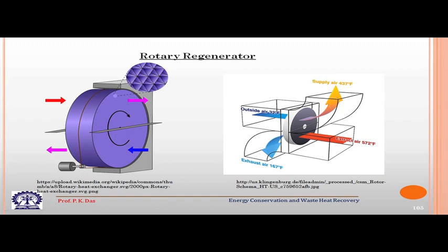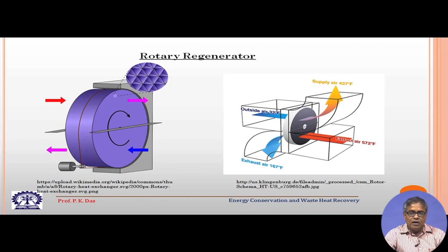In our earlier application, when we have seen the fixed bed kind of regenerator, we have seen that the beds are fixed and the fluid switches off from one bed to another bed. Here the fluid flow path remains constant, there is no switching off for the path of the fluid streams, but the regenerator is not fixed, the regenerator goes on moving in a circular geometry. So, it goes on rotating. So, this is for recovery of thermal energy.